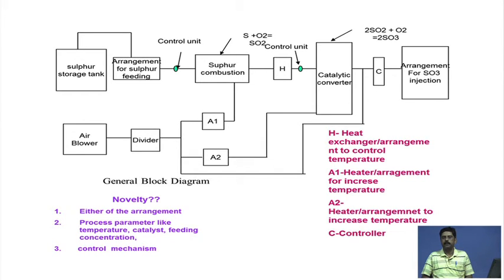The sulfur will get oxidized to sulfur dioxide, then sulfur trioxide, then it will react with moisture to generate sulfurous or sulfuric acid, and it will ultimately damage components because of acid dew point corrosion. So, they have designed some systems, and in that system, n number of components are involved.